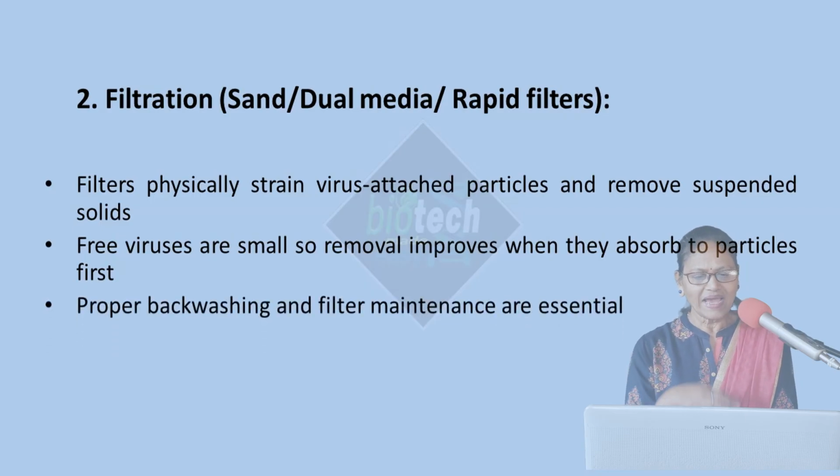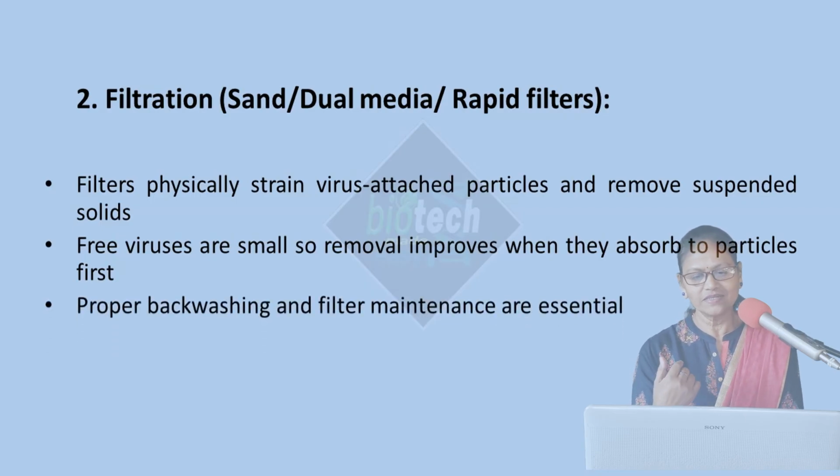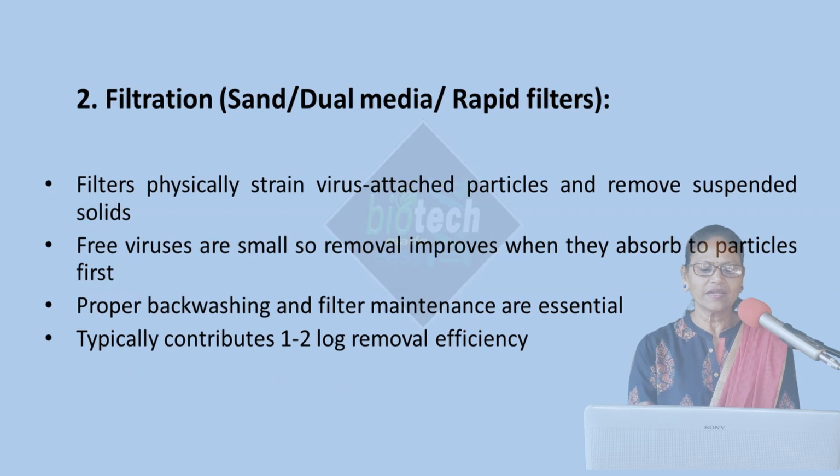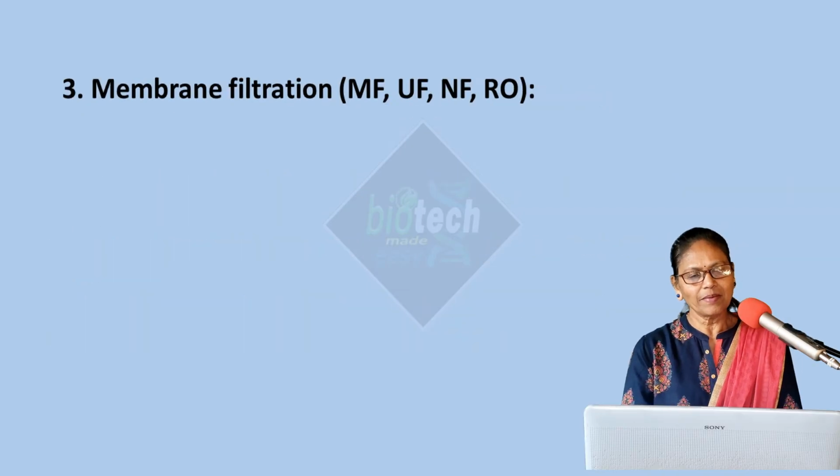Then proper backwashing, just to clean it, and filter maintenance are essential here if you have to do the filtration. And typically it can contribute 1 to 2 log removal efficiency. So the efficiency is 1 to 2 log. Then the third one is membrane filtration.